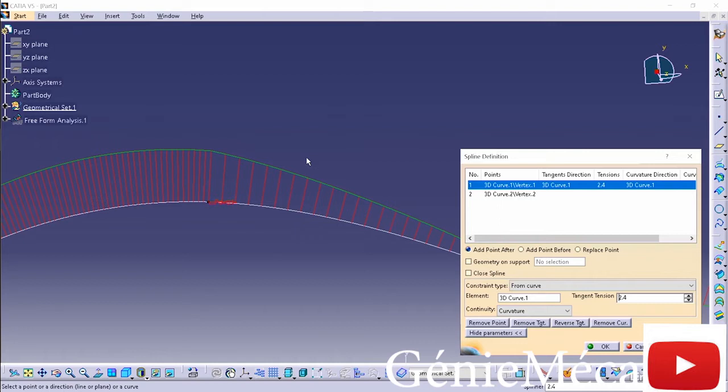When we're talking about tighter areas, small areas, maybe things in the interior, then G2 is acceptable if it's going to be something with a grain, maybe something that has not quite as bright or shiny a finish or wrapped in foam. G1, maybe with some acceleration like a conic or something along those lines, would also be acceptable. Again, if it's a small blend or a small fillet or tiny little areas and it's an interior, a lot of times a G1 condition is just fine.